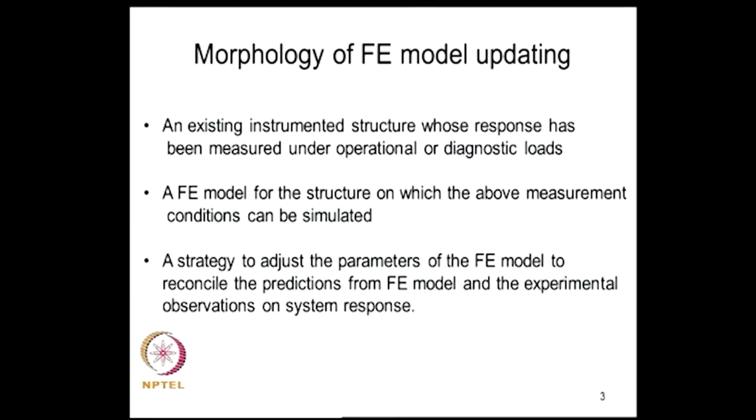Now, a typical finite element model updating process has, as I already said, an existing instrumented structure whose response has been measured under operational or diagnostic loads. By diagnostic loads we mean that we know what loads we are applying, and we have a finite element model for the structure on which the above measurement conditions can be simulated.